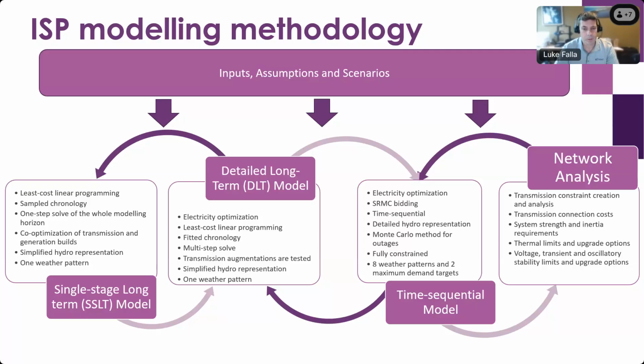And as we're aware that the time sequential model, again, is just a simplified representation of the full network model, we will bring that market modeling into a full load flow, like network analysis snapshots, to again check that things like peak demand days, high VRE, maximum interconnected flow periods do line up within the market model, and then iterate back to tune the model a few times to make sure that our output is robust.